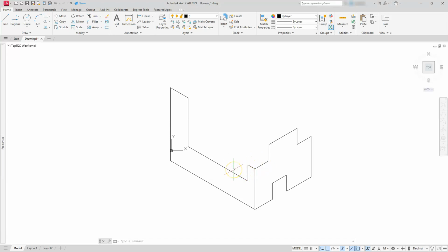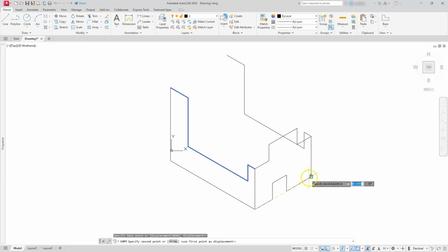So what I'm going to do next is use some of this to create the other stuff that I need, right? So I know how far it is across here. So I'm going to select a few of these lines and copy them as normal. So I selected these 1, 2, 3, 4, 5 lines, and then I'm going to copy them. So I'm pre-selecting them at this rate. Go to copy. I'm going to select this endpoint and place it on this endpoint.